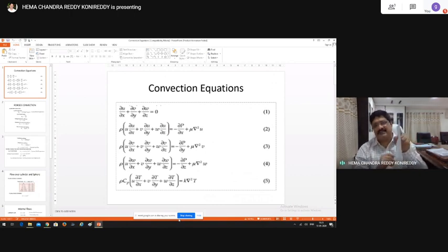If this is your vertical surface, if the surface is heated and cold air is there, the colder air, when coming in contact with the hot surface, gets heated up, and they vertically move. And while moving up, I said the first layer of particles which are sticking onto the surface, they sit pretty on the surface, and therefore the frictional forces will not allow it to move vertically upwards. But the remaining layers, as you move away from the plate, these layers will go. And again, when you move a considerable distance, the temperature difference will not be felt here, and therefore buoyancy forces are not there.